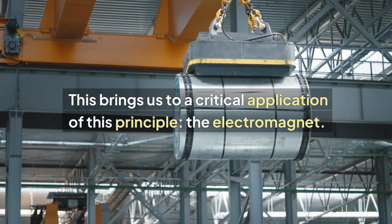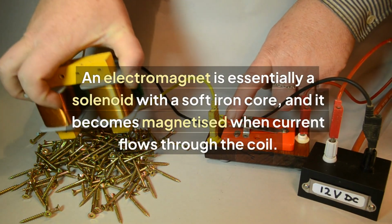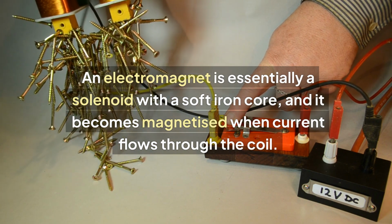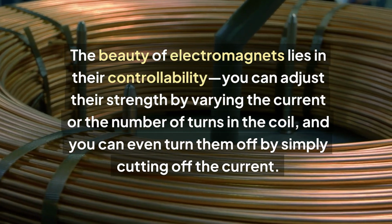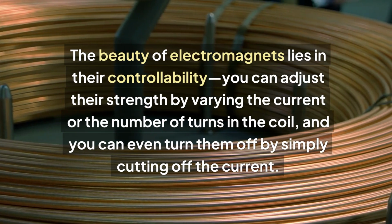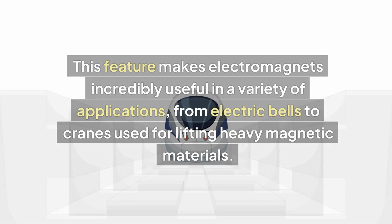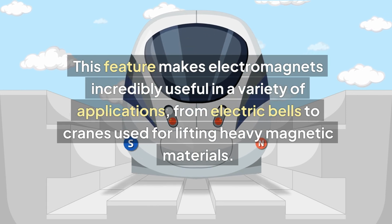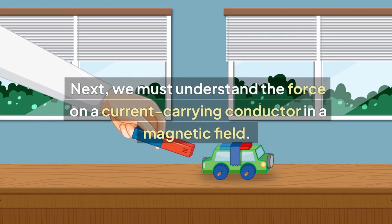This brings us to a critical application of this principle: the electromagnet. An electromagnet is essentially a solenoid with a soft iron core, and it becomes magnetized when current flows through the coil. The beauty of electromagnets lies in their controllability. You can adjust their strength by varying the current or the number of turns in the coil, and you can even turn them off by simply cutting off the current. This feature makes electromagnets incredibly useful in a variety of applications, from electric bells to cranes used for lifting heavy magnetic materials.